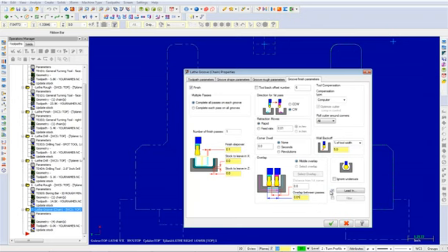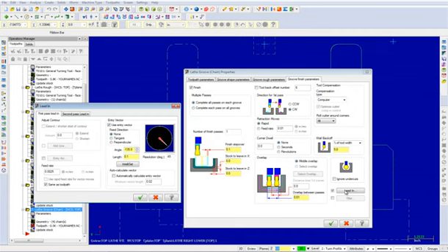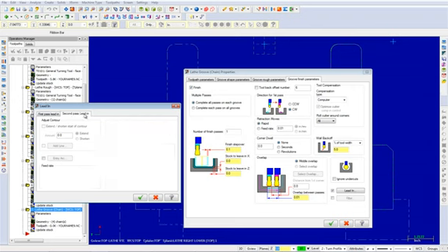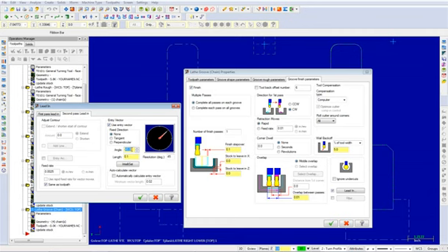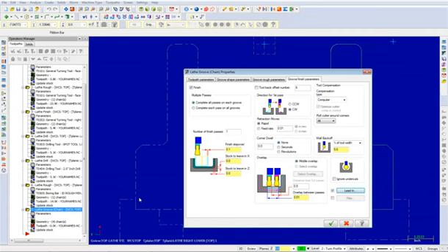Now select the Lead-In button. Set the first pass and second pass lead-in entry vectors to -90 degrees. You can now select the OK button to exit the lead-in dialog box. Again, select the OK button to exit the Lathe Groove dialog box and generate the toolpath.